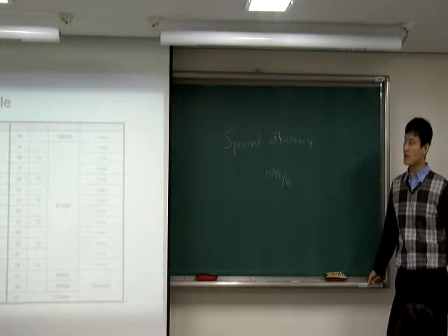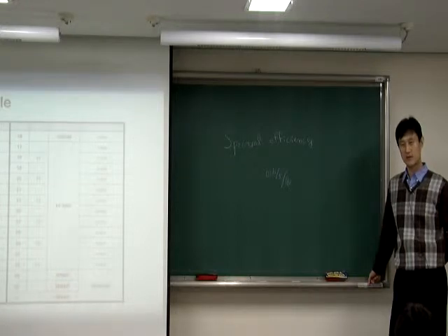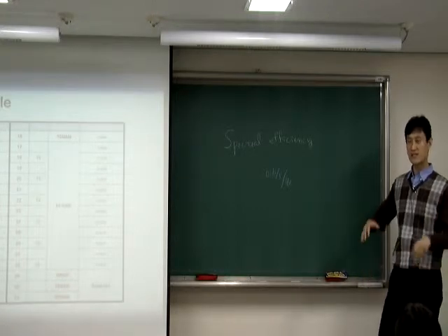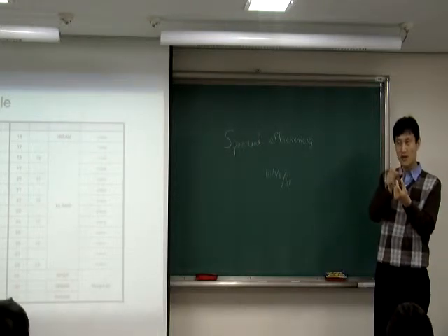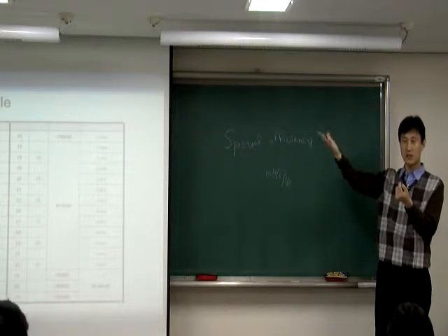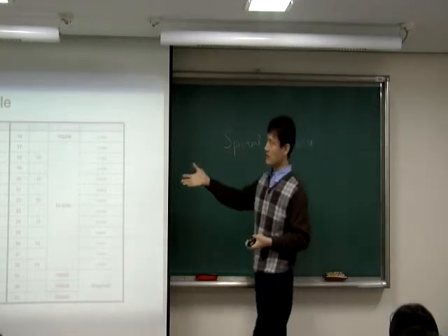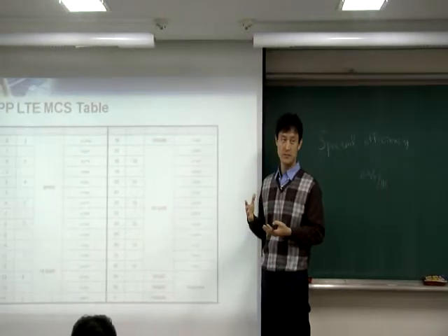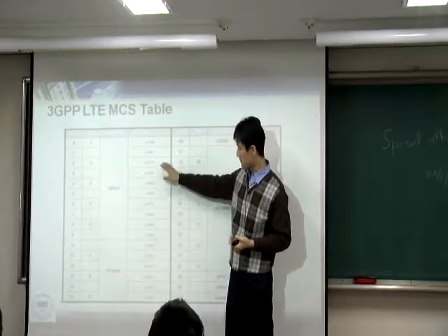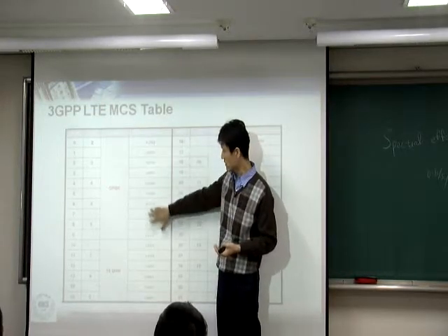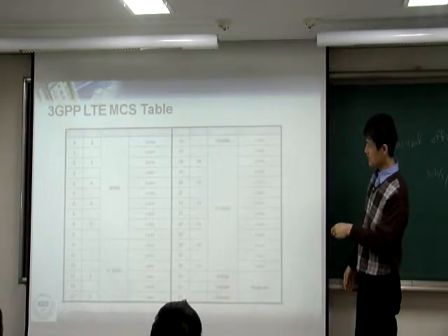From all the knowledge that we have learned so far, the best way is MIMO, right? In MIMO, you basically extend into the space dimension. Therefore, you can use the same 1 hertz, but we increase the space domain, so you can increase the BPS. But the adaptive modulation and these things help too. So this spectral efficiency actually has to be calculated, and it gives pretty fractional numbers.